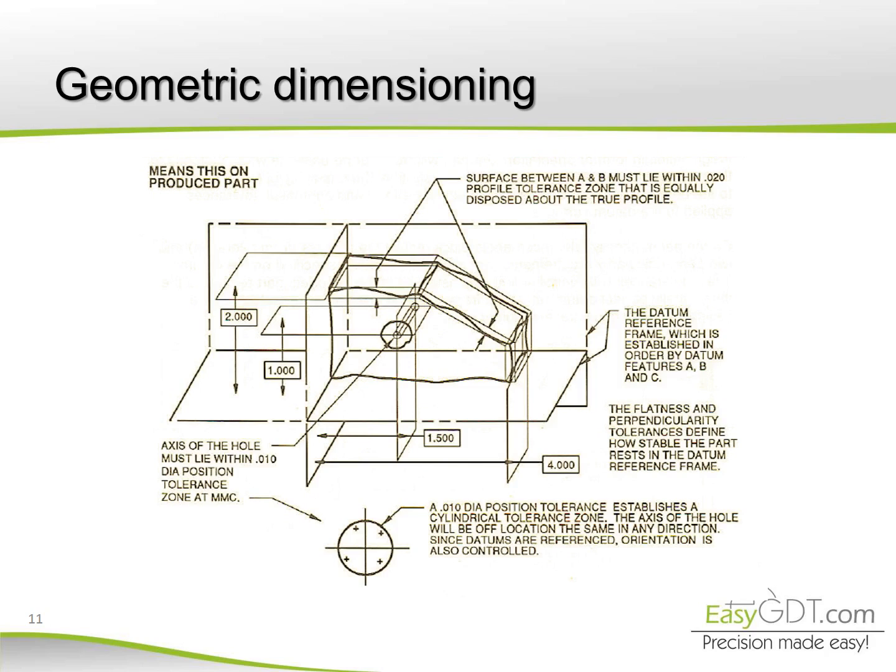Now, here are the tolerance areas of geometric dimensioning method. The shape of the part can be controlled by a geometric control of profile. Take a look at the hole. See how the tolerance zone described by this method has a circular shape, which is more functional for ensuring assembly between holes and counterparts. You can also see the restriction of the part is described by datums, a fundamental concept that we'll discuss forward.